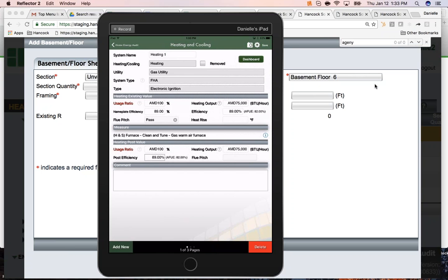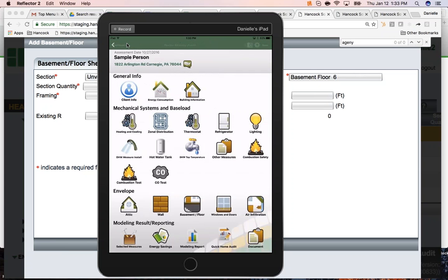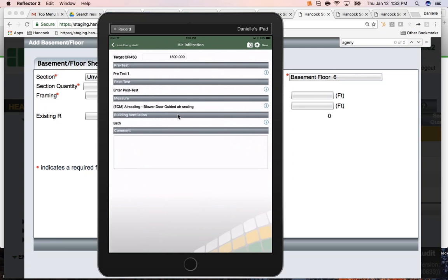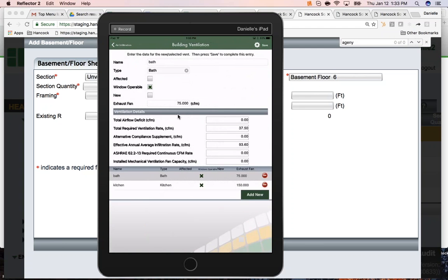There is a question, and that's a good question. Chris asks, before we leave that ASHRAE 62-2013, the kitchen affected definition, I think, is 150 CFM or less. Yes, and maybe I'm checking now. I believe that's what it is. Okay, Art, you can just type it in the chat box to everyone. But I think an affected kitchen CFM is 150 CFM or less.